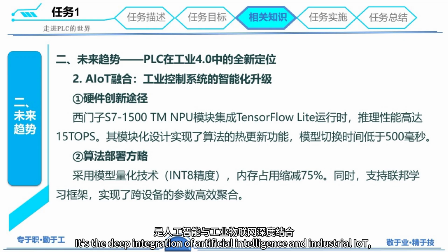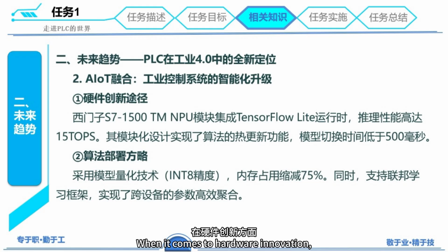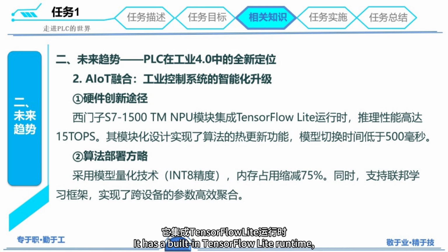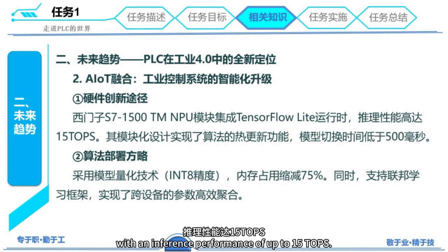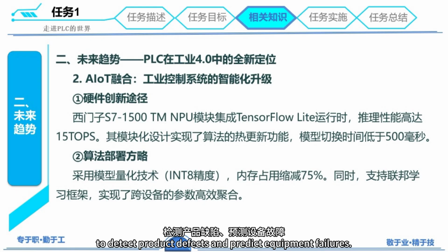It's the deep integration of artificial intelligence and industrial IoT, turning PLCs from simple control devices into intelligent decision-making devices. When it comes to hardware innovation, take Siemens S7-1500 TM NPU module as an example. It has a built-in TensorFlow Lite runtime with an inference performance of up to 15 TOPS. It can directly run AI models right there on the industrial site to detect product defects and predict equipment failures.